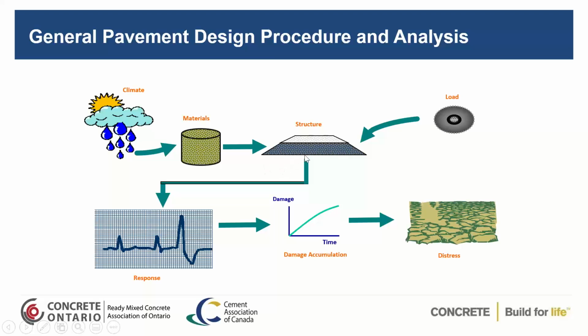What is that pavement structure going to look like? Do you have to design for frost because you have a very high frost penetration, so you might need a little bit more granular? What type of soil conditions do you have to build your structure on? You're going to have to look at that, and I have a slide on that shortly. But you have to look at your pavement structure. Then you have to look at what the loading is going to be on that pavement structure.